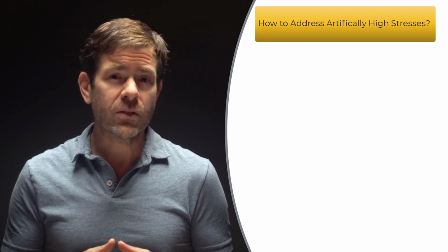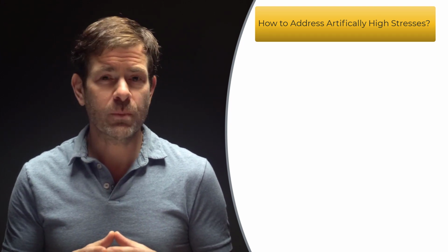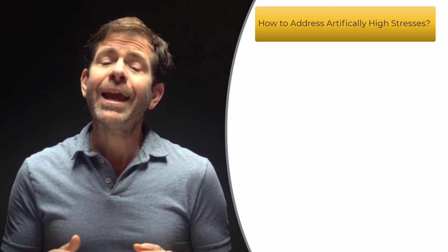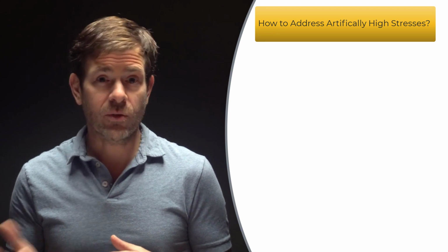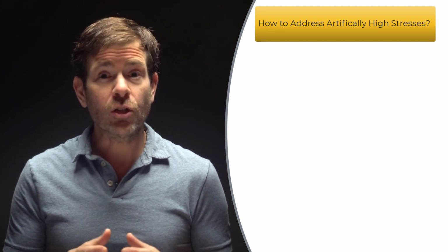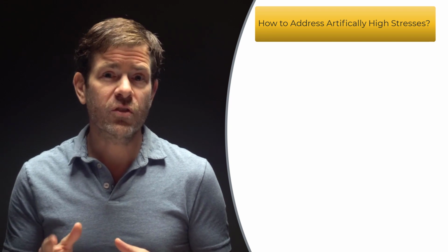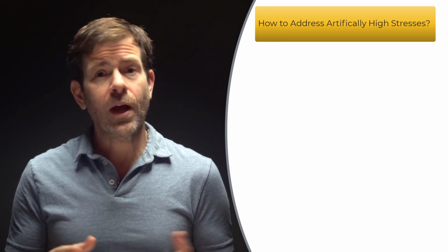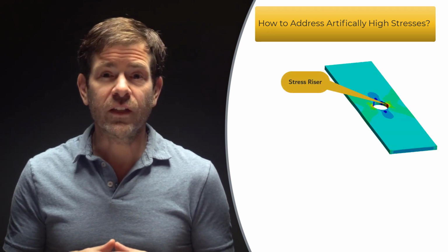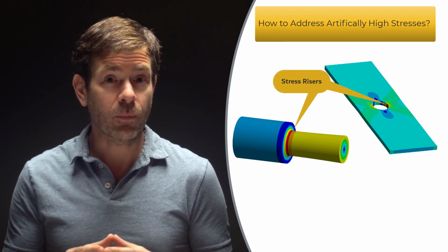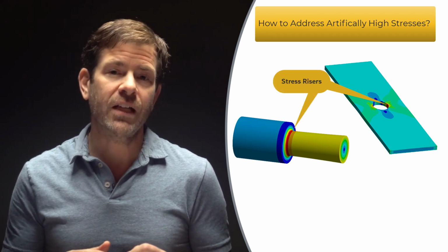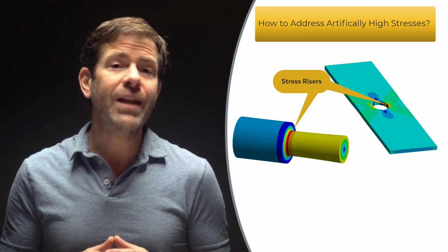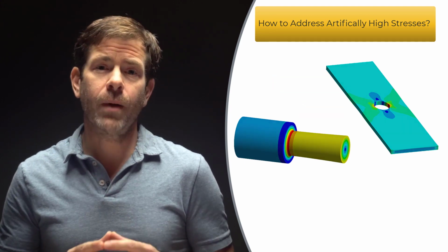Finally, when evaluating stress results, take care to understand the difference between a stress singularity, such as the case we discussed with re-entrant corner, and a stress riser, also known as a stress concentration. Stresses that look artificially high may be legitimate, so spending time to understand and doing a mesh convergence study is recommended. Stress risers such as a hole in the plate or a fillet on a step shaft, just to provide two examples, will have larger but finite stress. These may even have a closed-form mathematical solution and should not be ignored as artificial or artifacts of the model.